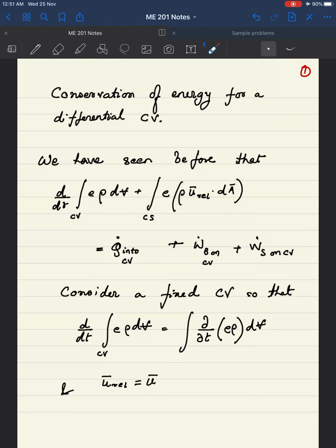Okay, so with regards to the energy equation, now the energy equation is simply a conservation of energy for a differential fluid volume or control volume, and it can be derived in multiple ways. You can either take a differential control volume, which is, let's say, dx, dy, dz in size, and then do the conservation, make sure that all the fluxes, etc., are written properly, and then just account for everything and get that equation.